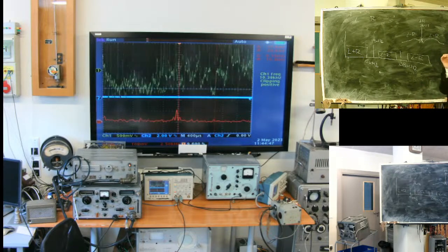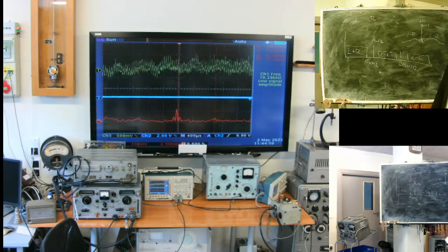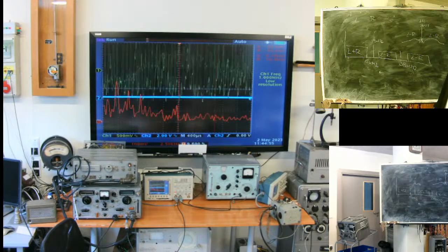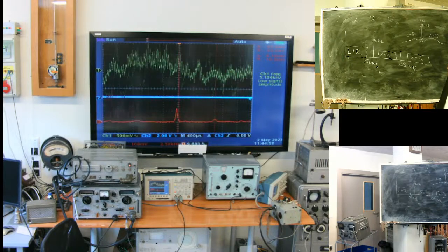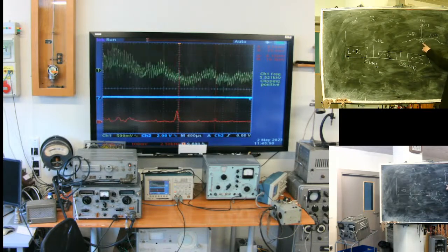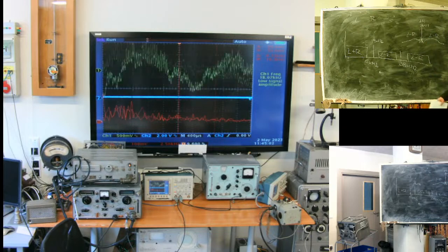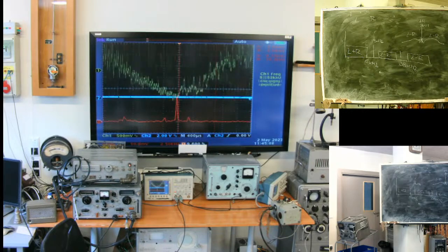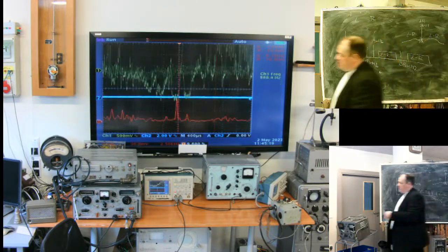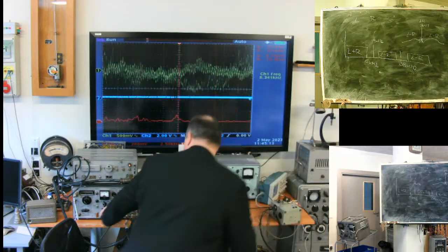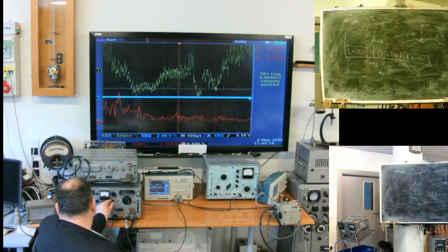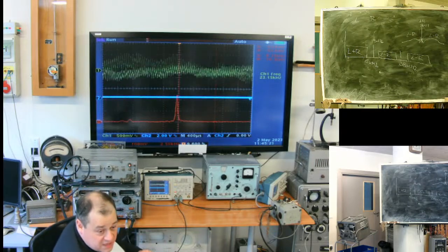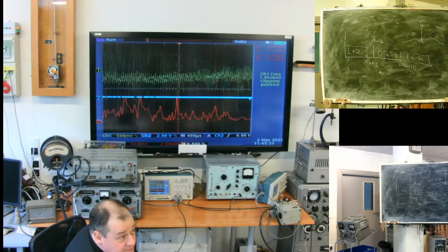See how the signal is packed. Sound one, left plus right. Then with balanced modulation, left minus right is put around 38 kilohertz, and all this is used as a complex signal to modulate, in my case, what frequency? Where am I at this moment? A 99.4 megahertz signal, and then it's transferred to us.